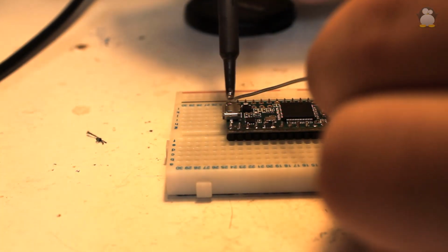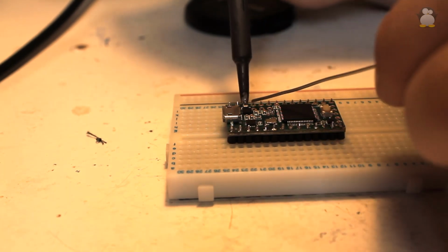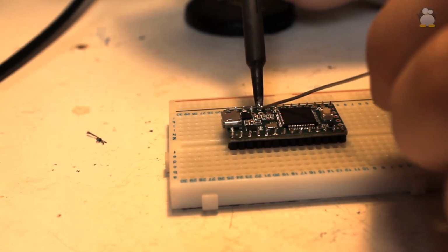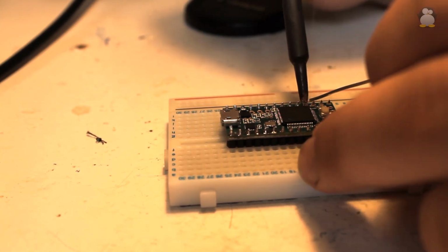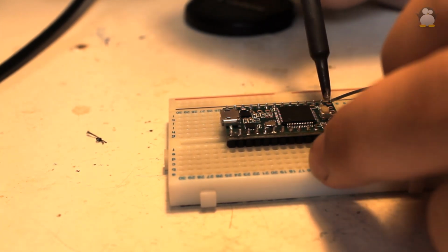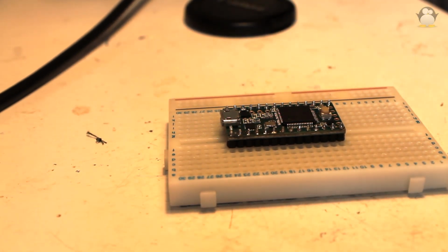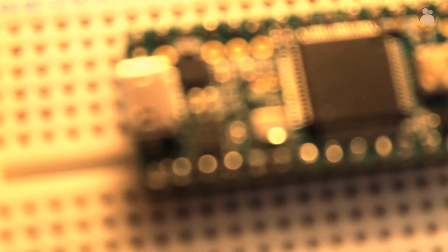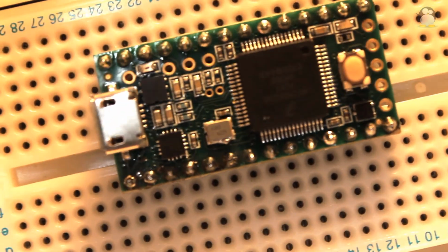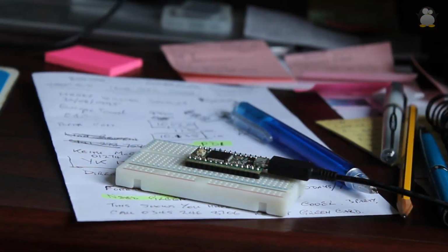The Teensy will come delivered with header pins that need to be soldered into the board. Here I'm using a piece of breadboard to hold the pins in place whilst I do this. And you can see that I've not soldered the vertical pins in. That's because in breadboards like this one, the vertical pins wouldn't fit and we don't need them anyway, so I've left them out. When the Teensy arrives, it will come preloaded with the blink program.